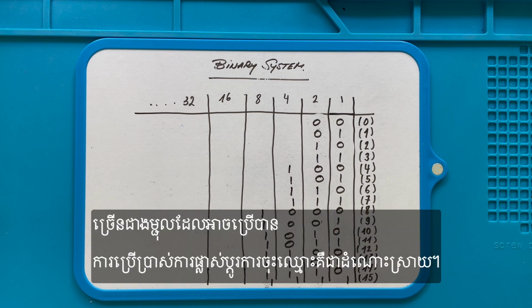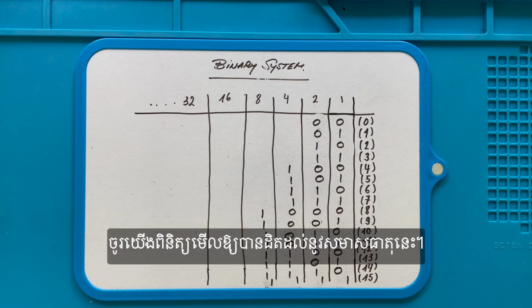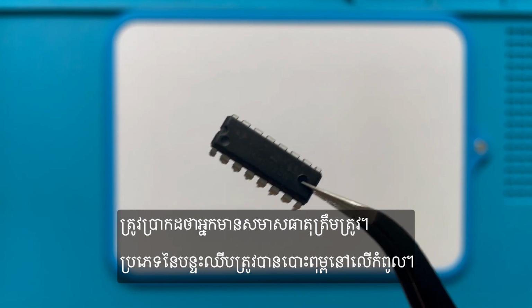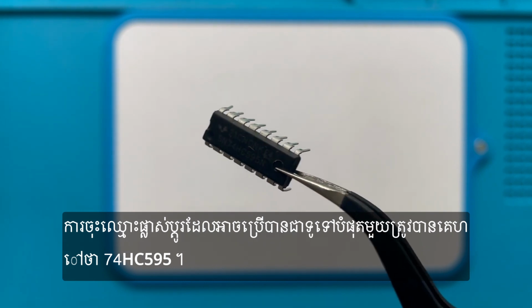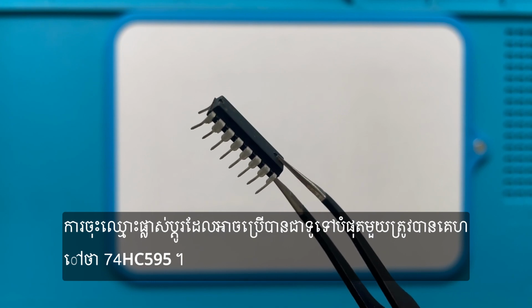But once there are more LEDs than available pins, the use of a shift register is the solution. So let's take a closer look at this component. Make sure that you have the right component. The type of chip is printed on the top. One of the most commonly available shift registers is called the 74HC595.